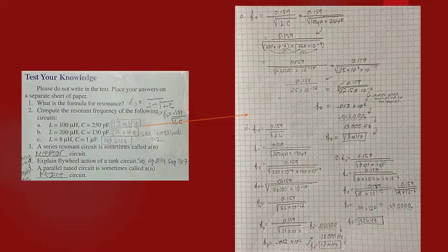Basically, we take the source out of the equation, and we close switch 2, where your capacitor is connected to your inductor, and they are in parallel. They're right next to each other, right across from each other. So once we close this switch in between them, the capacitor, the first thing it's going to do is discharge. It's going to discharge in the opposite direction of the flow of the power source. The flow of current will flow opposite from what the power source flowed just earlier when the other switch was closed, and it will charge the inductor.